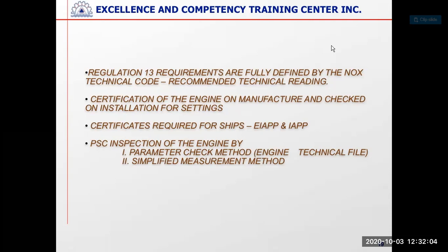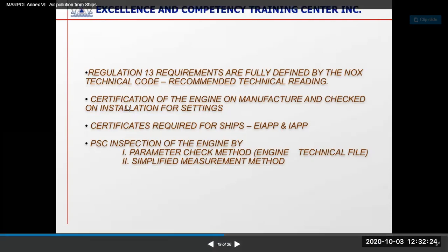So there is a special NOx technical code which is an attachment to MARPOL, because there are a lot of special clarifications and requirements for the engines to reduce NOx emissions, and there are recommended readings for each type and RPM of design of the engines by different groups. And the certification of the engine as per the manufacturer should be checked before installing them, and all the settings.